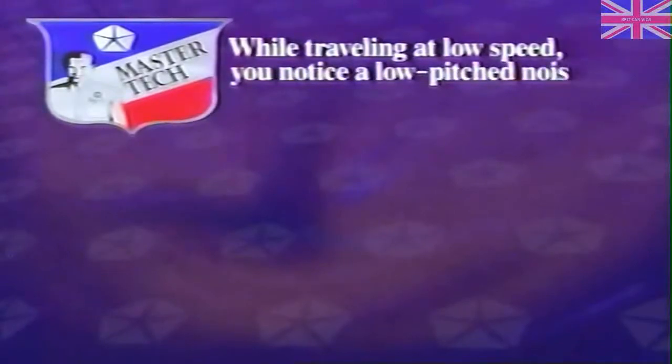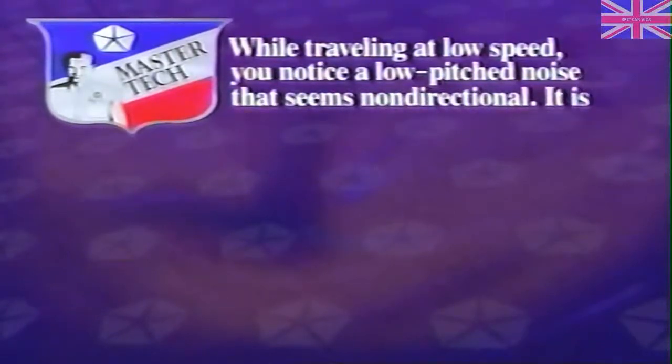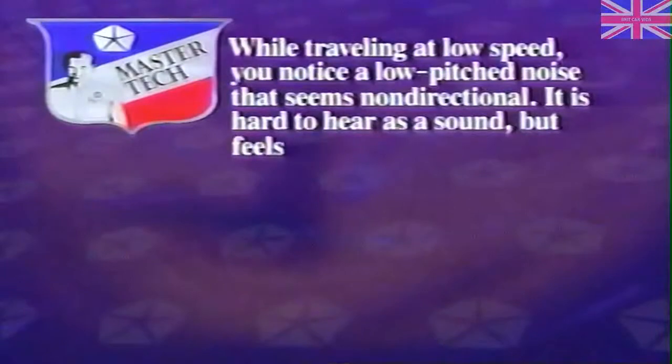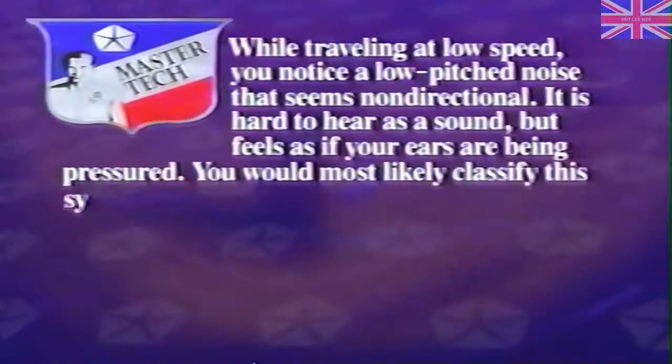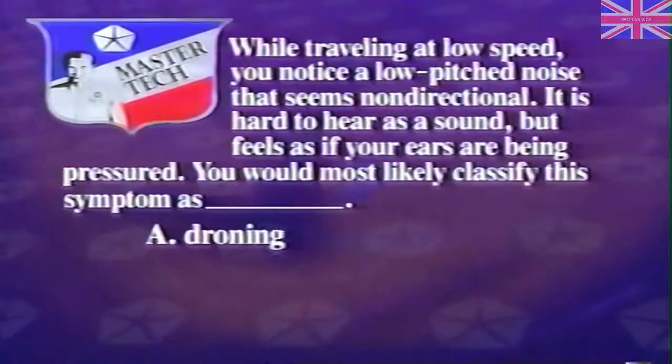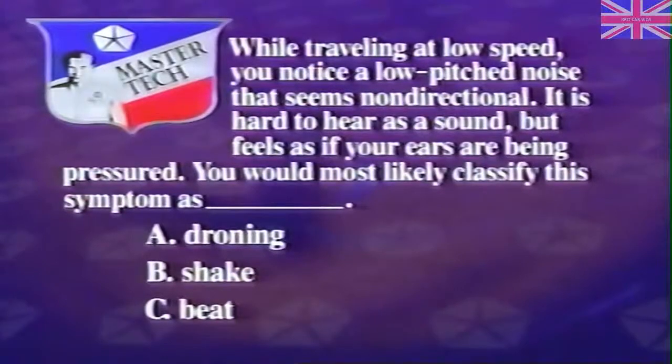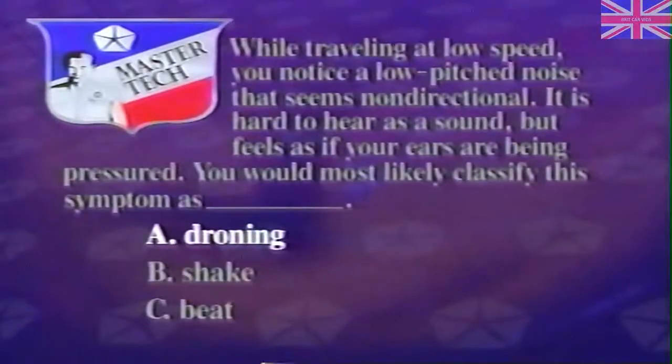While traveling at low speed, you notice a low-pitched noise that seems non-directional. It's hard to hear as a sound, but feels as if your ears are being pressured. You would most likely classify this symptom as A, droning, B, shake, or C, beat. A, droning is the correct answer. Let's proceed.